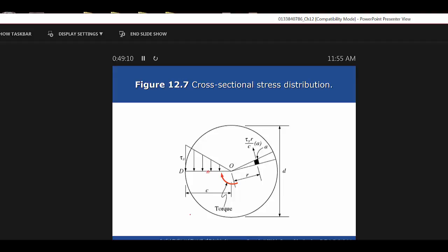I mean, you can break a shaft anywhere. It doesn't necessarily have to be at the thread. In the case of your bolt, it's more than likely going to break there, but I've sheared bolts off that I haven't actually sheared at the thread. Yeah, you can do that. There's something else that made that happen. It might have been rusty, or it might have had a nick in it, something like that.